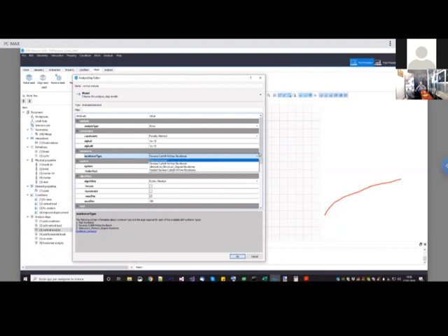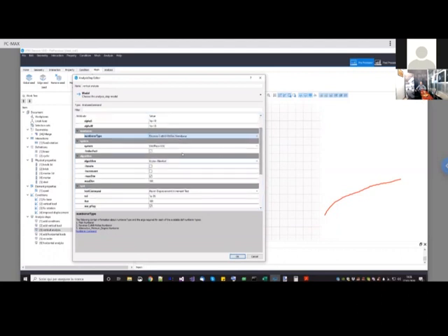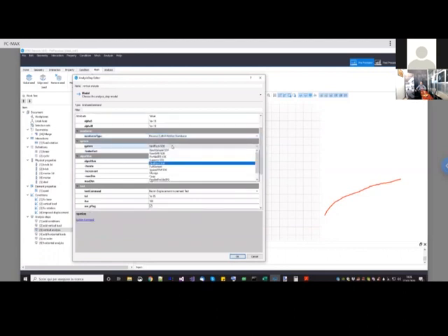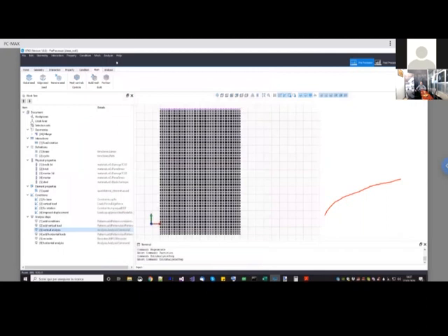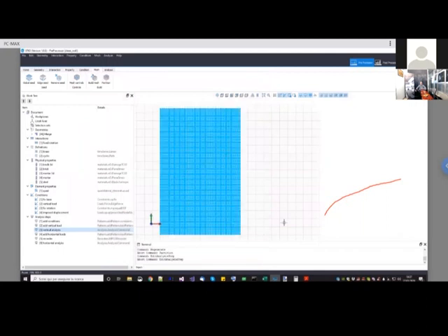Okay. And the last change should be done in the system because you need to choose the MUMPS or the parallel profile SPD. But unfortunately, the SPD is only for symmetric and positive definite matrices. So in your case, you should choose the MUMPS. So when you're done changing the numberer and the system, and you partition your mesh, you can do your analysis in parallel. And it is quite efficient.